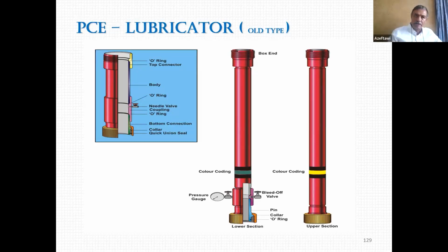What is your bottom hole assembly? It is the tools that you are running. From the top, the first thing you have from the slick line is what we call the rope socket, which is the connection from the wire line or the E-line. The slick line gives you a thread at the end so you can connect your tools.